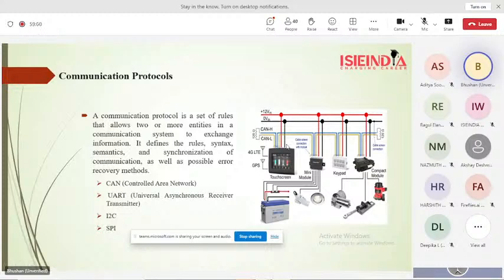If you connect n number of connections in series in the CAN protocol, no disturbance will happen. That much burst and that much efficiency happens in the CAN protocol. UART, universal asynchronous receiver transmitter, is used but only for low frequency ranges, not high frequency ranges. I2C and SPI are also not for high frequency ranges, so they are not used in the electric vehicle battery management system.